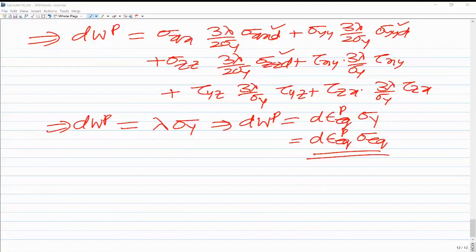If you use the global coordinates, then for different elements the expressions for the shape functions would be different. Although finally the stiffness matrix would be the same in terms of the length of the element along x and y, Young's modulus, Poisson's ratio, thickness, the expressions for the shape functions would be different if you use global coordinates, because the global coordinates for different nodes of a particular element are going to be different. Okay, sir, so till now, in all the cases, we have assumed the local coordinates while forming the KE. Yes.